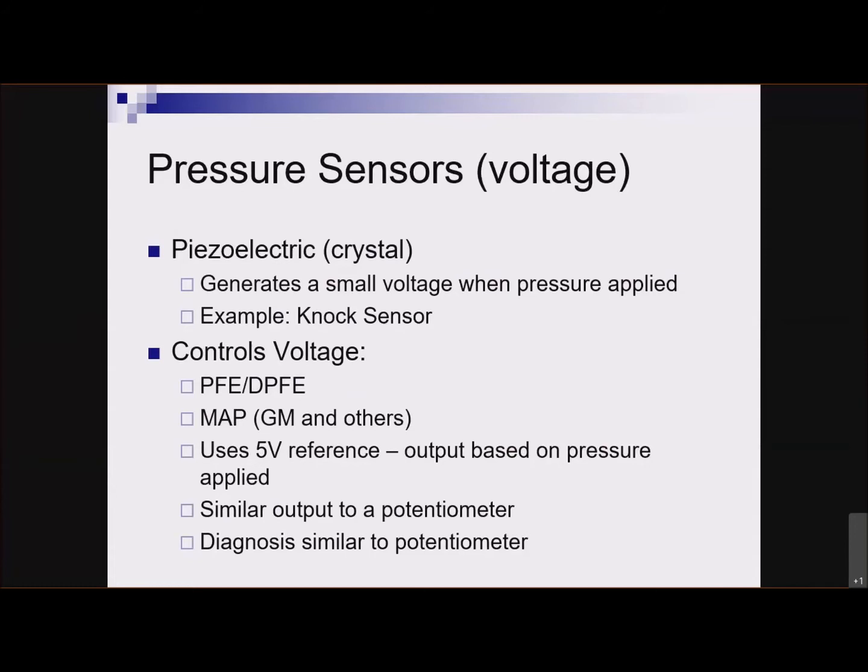They were used to more accurately measure exhaust gas recirculation flow by looking at either pressure in that EGR tube, pressure in a tube hooked to the exhaust, or pressure in two tubes up to the exhaust, and then measuring the difference between those two. Probably most common, MAP sensor, but also fuel tank pressure sensor. They frequently look very similar.